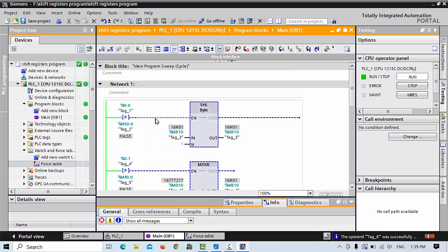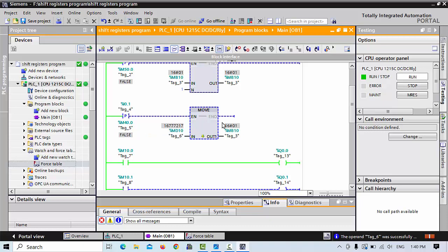So in these areas this command is very helpful. For example, I0.0 is your first signal to fill the 500 ml bottle, and the second bottle maybe comes at 250 ml. You put in another sensor, which is I0.1. When that signal 1 comes, you can move any other data register, how much value, maybe a timer you can use with this command. When the next signal comes, if you need any other value, you can move that value. It is very helpful in this program logic.